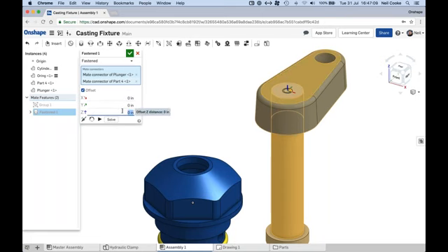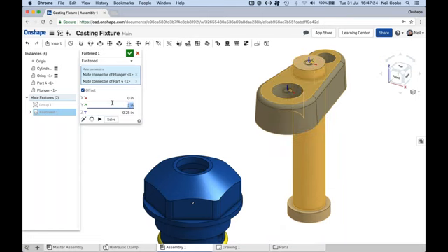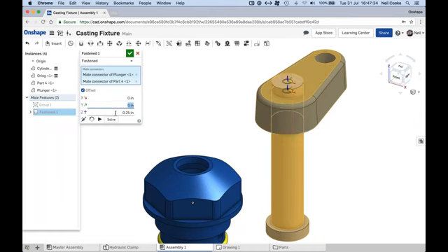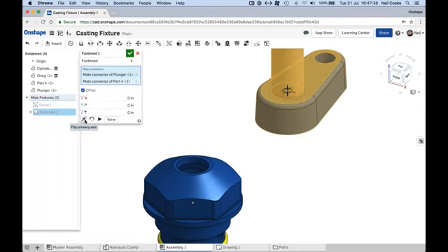So if you want to offset it, so minus 1/4 inch, or in fact plus 1/4 inch, if you want to offset it a certain amount, then you can type that in. And obviously, if you start doing something like that, it will actually put it in an offset location. But again, it's easier to do that if you are restricted in the location where you can place a mate connector.